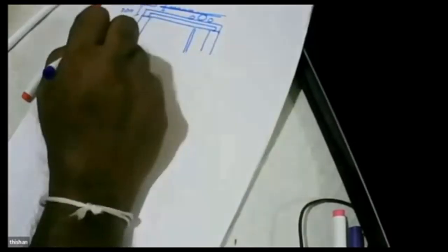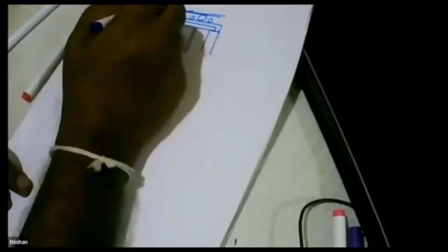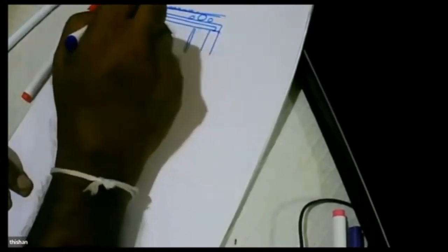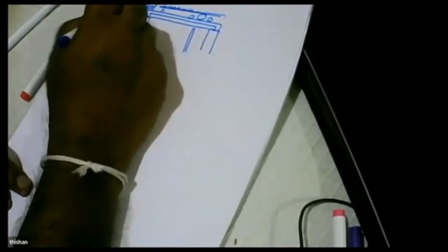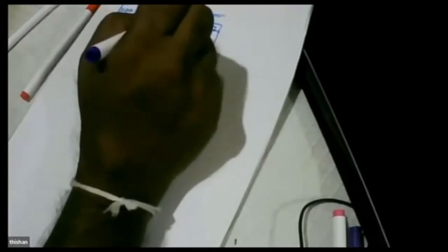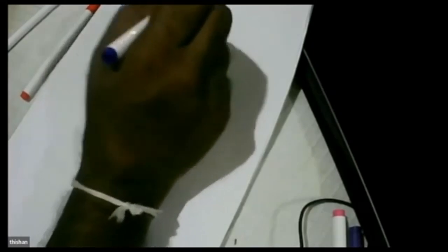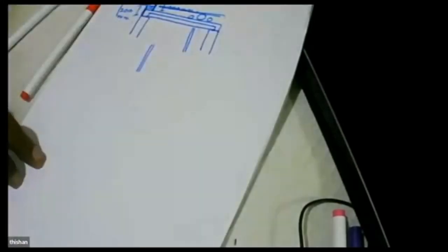So because this allows us to make a drop of 200 millimeters, of course we have to build it when you are doing the slabs. So what you do is you fix a timber plank, and because this slab is supported, we can fill the concrete when this concrete is done. So basically we can minimize the need for any horizontal chasers in the walls, because most of the plumbing work can be kept as vertical as possible.